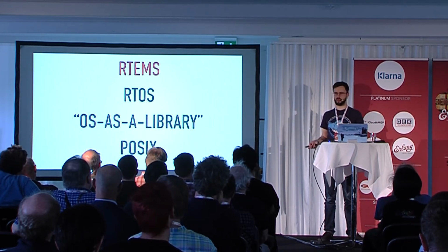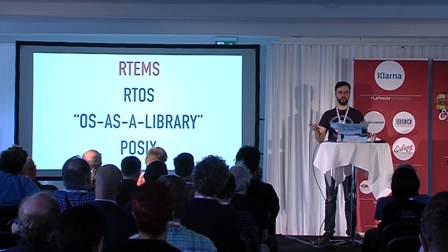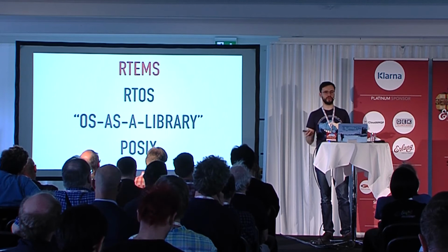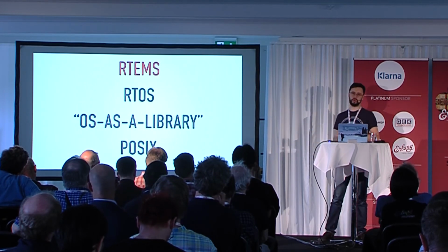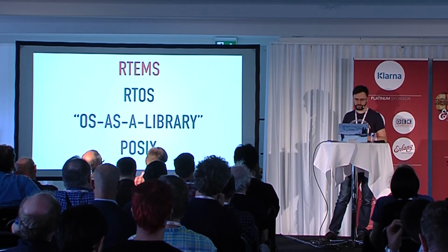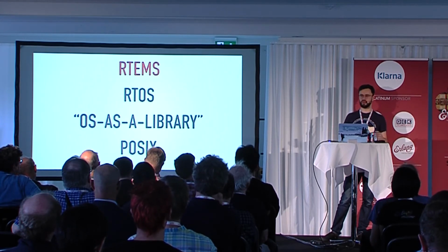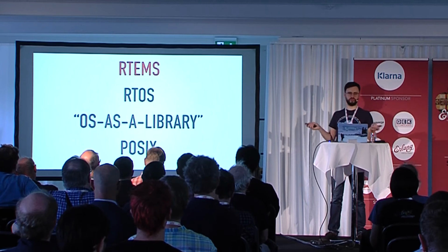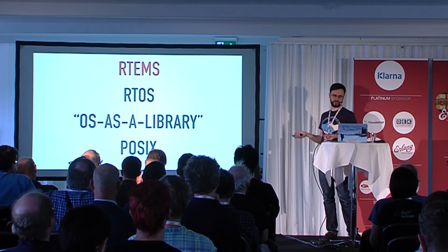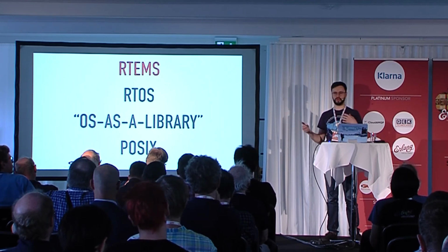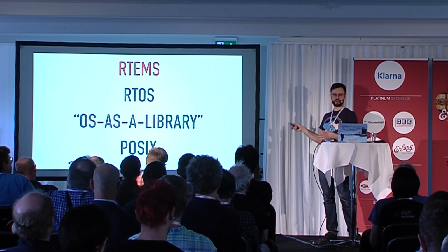If you write a C program and you link in RTEMS, you still get your C program with lots of libraries behind it. Then you can actually boot from this program directly on the processor, and this is what we're doing with the Erlang VM. It does support standards like POSIX, so operating system APIs. This is why for us it's perfect, because Erlang uses POSIX, so we can just combine it with RTEMS, and whenever Erlang makes a syscall or a POSIX call, RTEMS implements this for us.